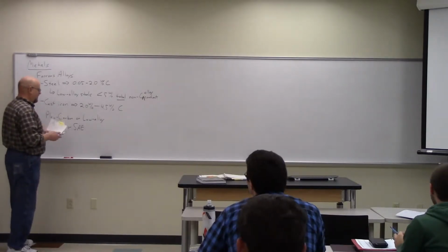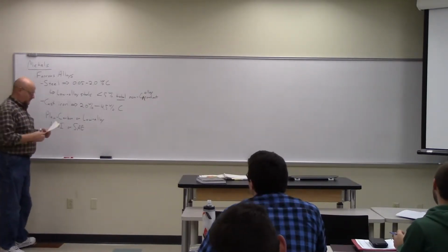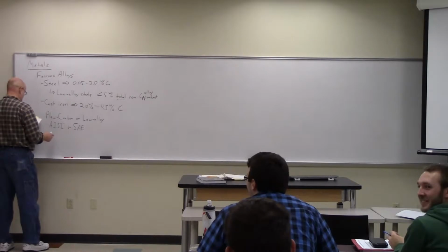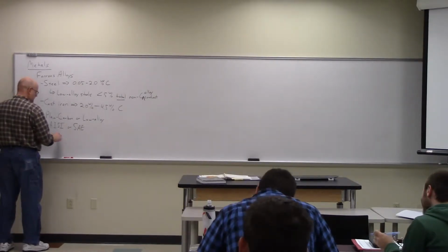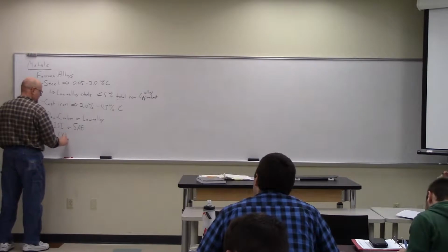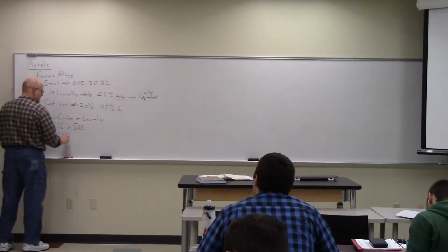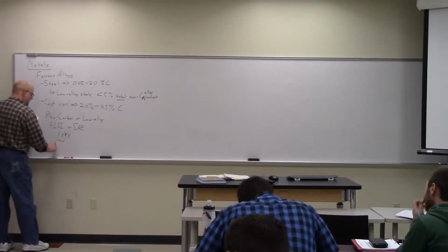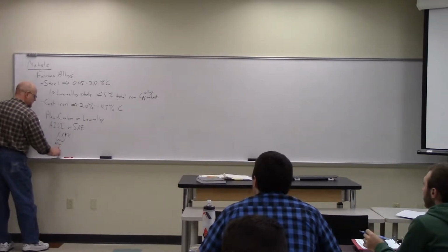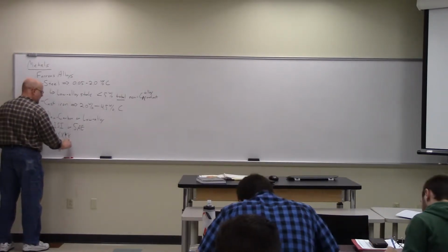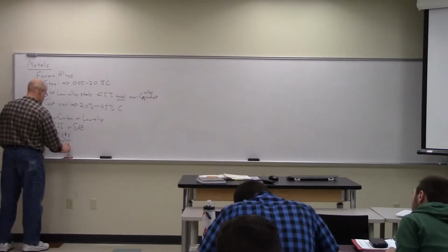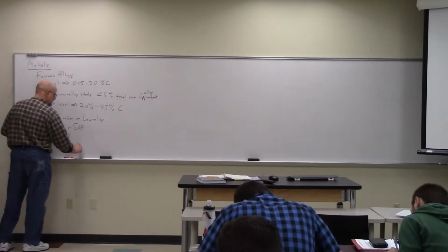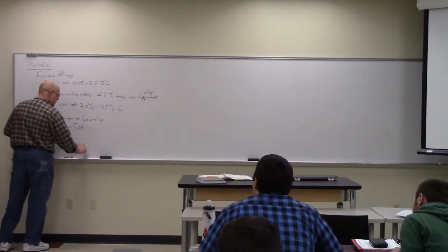Society of Automotive Engineers. There's two different ways of designating materials, okay? The general consensus is you use XXYY format. The XX is the alloy type. The YY is the percent carbon. And it's done in 0.YY%.